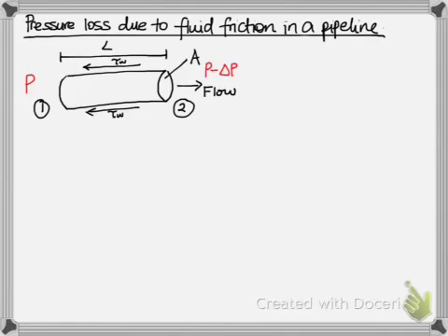We're going to have two forces acting in this pipe. Since we have flow moving in the first place, we must have what we're going to call a driving force. The driving force is what is causing the flow to go from left to right in the first place, and we're going to symbolize this as FD.